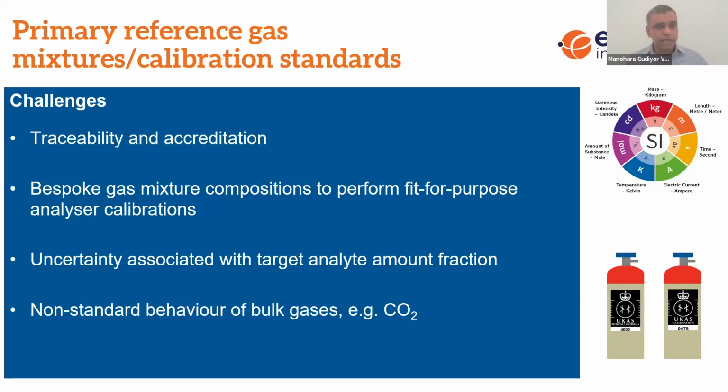The biggest problem that we experience, and that everybody should expect, is the non-standard behavior of CO2 itself, because it has a very challenging pressure-temperature phase diagram. You may not have a lot of freeway as opposed to natural gas, hydrogen or any other gas. So here you need to be very careful in designing these primary reference materials.